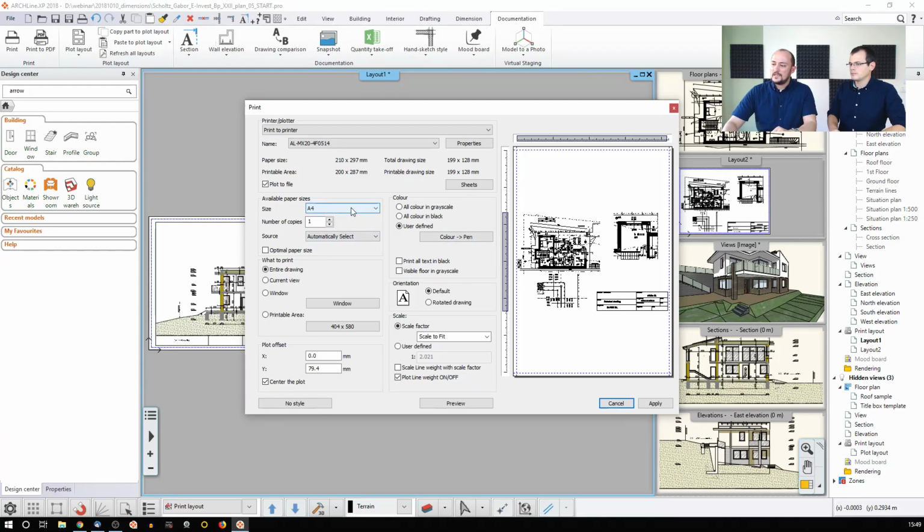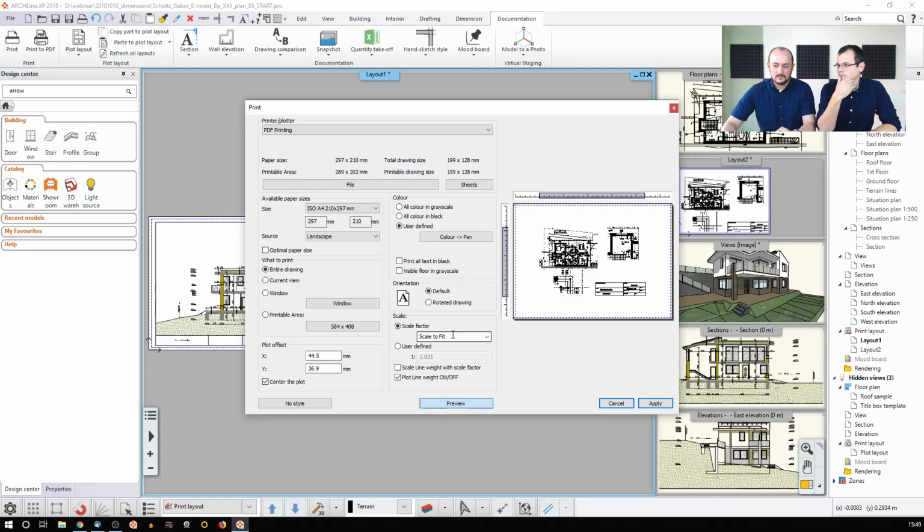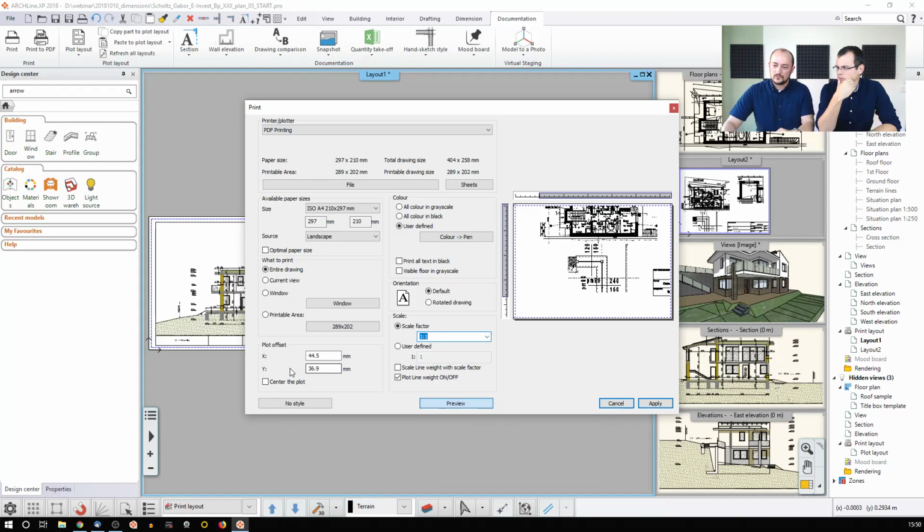This is, I believe that was A4, but it was landscape, I believe. And I should not print to this printer now if you would not see the result. So I should go with this one, and then just A5 landscape, center it again. And then, yeah, it should not be scaled to fit, never. It should not ever be scaled to fit. If you would like to print something for engineering documentation, you should always pick up any of these. That's in this case 1:1, yes.